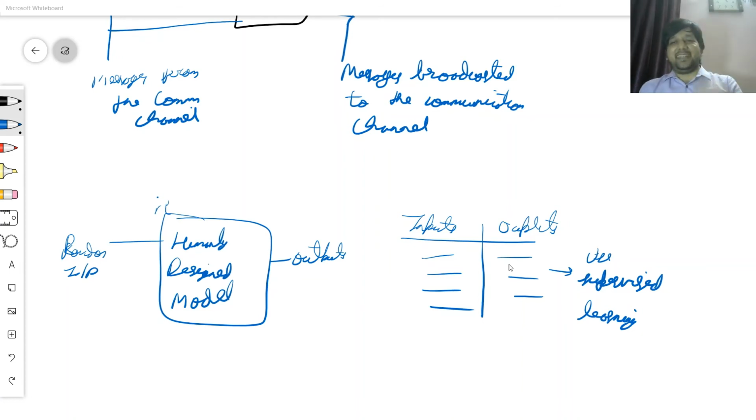Let it run day and night. As the robot is running, you are populating the database. The inputs and outputs are getting populated in your simulation setup. This data table is getting populated and you're simultaneously learning from it. So it's incremental learning. You also don't need to store it. You can simultaneously learn it with a neural network. So a neural network is using the artificial potential field to move the robot and make a training data set, and it's simultaneously learning from such motion, from such observation.